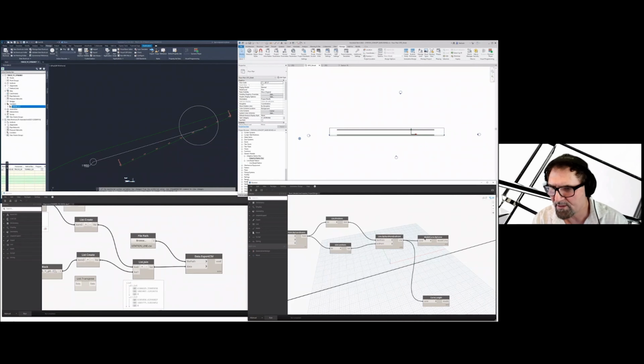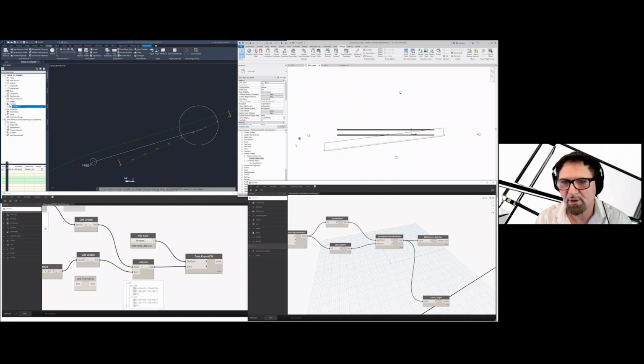And then we're going to go to Revit and create a model curve, even though it's a line. And so that quote unquote curve is one object, right? And over here, we have the coordinates for the line. So the curve is created from this line, and you can see it here in Revit. That's the curve that was created. However, I haven't updated it yet. So when I click on run here to run it, it will read the information from that CSV file and update the geometry. Now that geometry is updated.